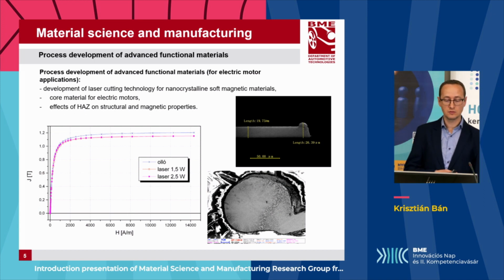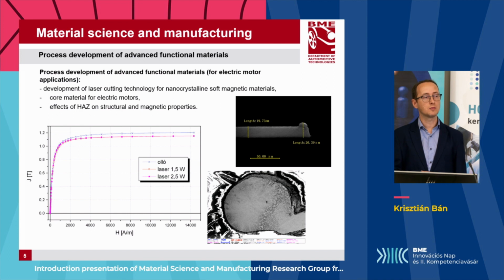In the field of advanced functional materials, we developed a laser cutting technology for amorphous and nanocrystalline soft magnetic alloys. In this development, we examined the effect of the heat-affected zone on the structure of the material and the magnetic properties of the material.